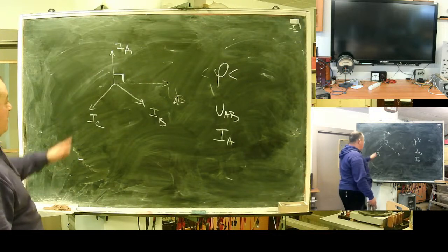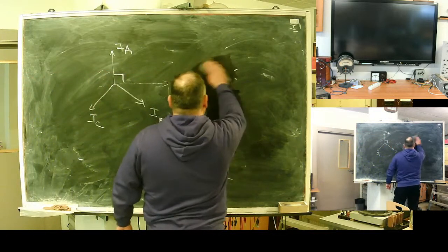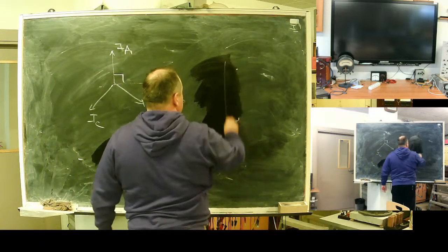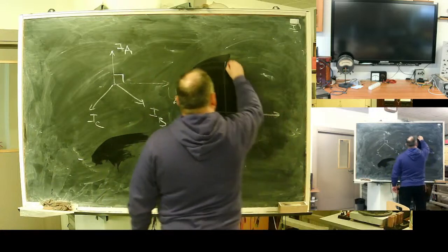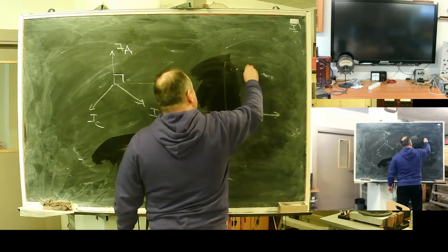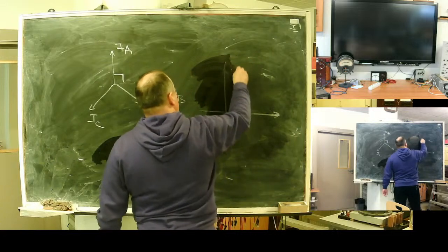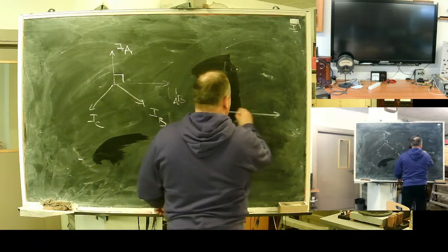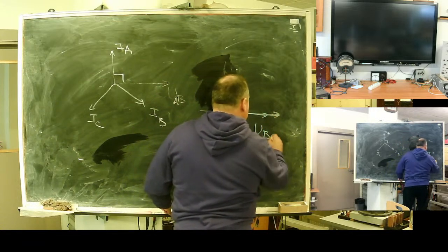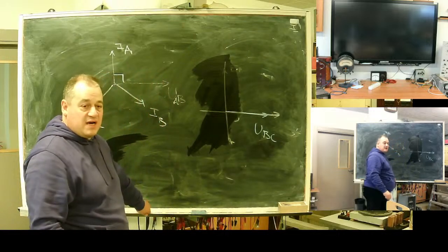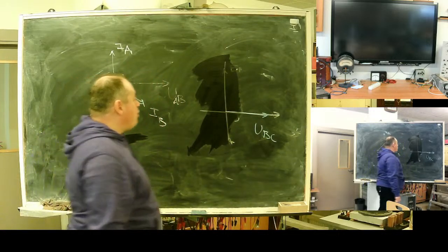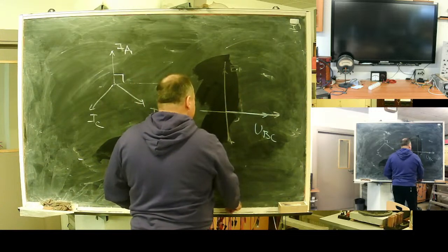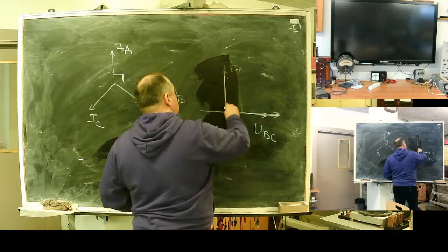Now, if I do like this, what kind of characteristic will I need? Let's say this is A phase EMF. Yeah? This is polarizing, polarizing voltage BC. Possible currents in case of fault: loop resistance is pure active.